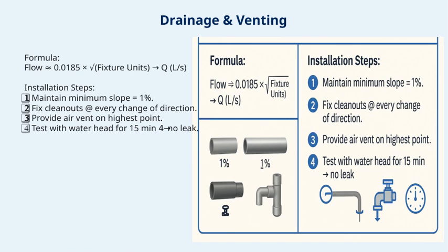Finally, always test your system with a water head for at least 15 minutes to check for leaks. If there's no leakage during this test, it indicates your drainage and venting system is properly sealed and ready for use. All these steps help ensure your plumbing functions smoothly and reliably.